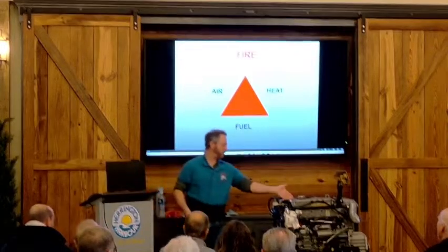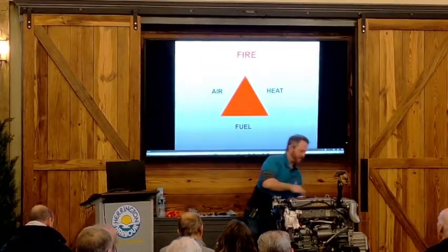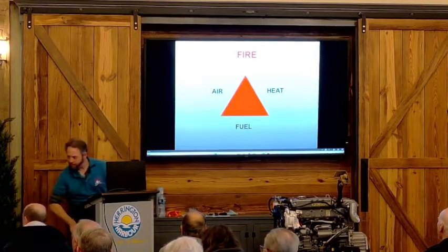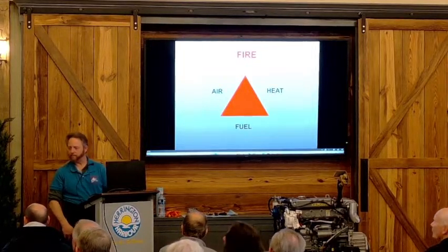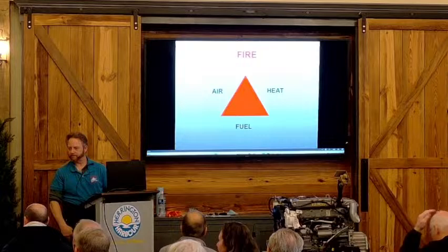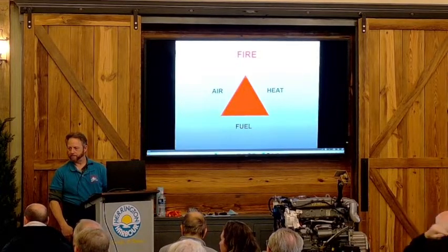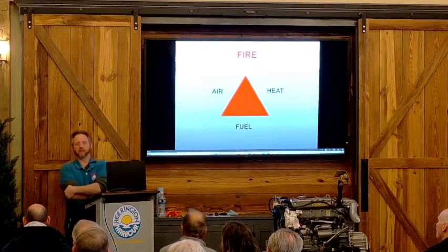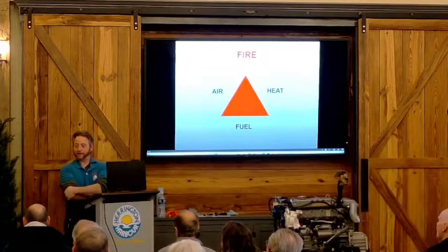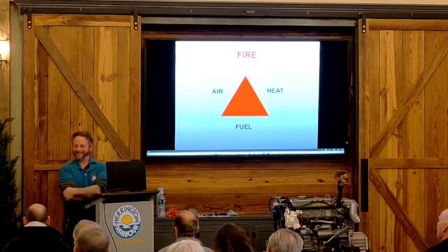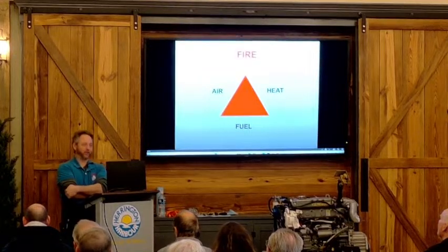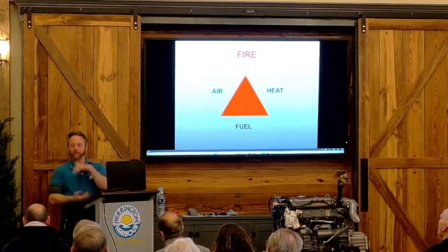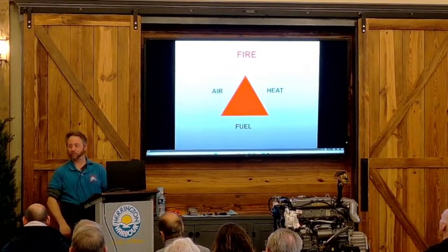Yeah, so this engine doesn't have glow plugs and doesn't have the air heater either. So you're showing signs of some age. If you have trouble starting your engines in the spring and fall because the outside temperature is dropping, that means your compression in the cylinders is probably borderline low.